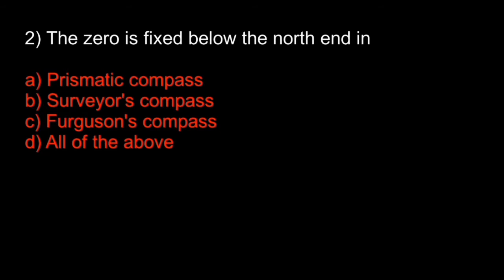And leveling: the instrument has to be leveled if it is used in hand or mounted over a tripod. If it is used in hand, the graduated disc should swing freely and appear to be completely level in reference to the top edge of the case. If the tripod is used, they usually have a ball and socket arrangement for leveling purpose. Prism can be slid up or down for focusing to make the readings clear and readable.